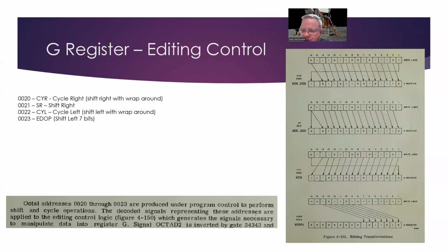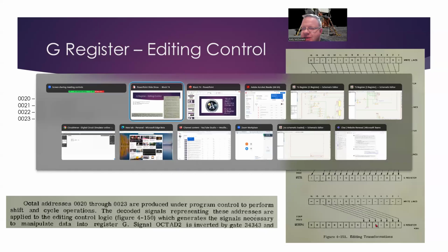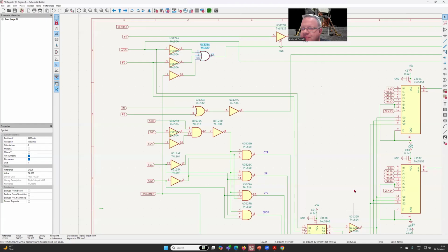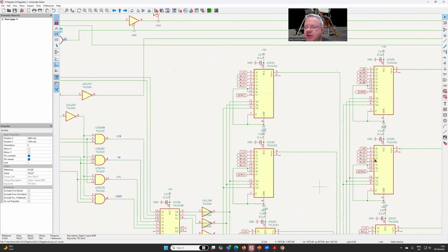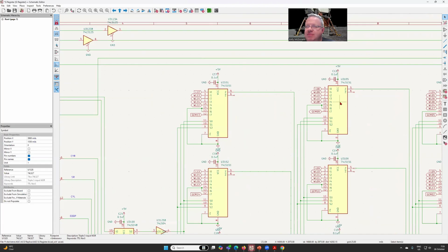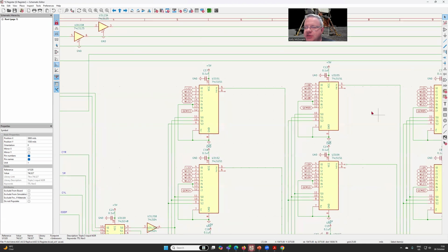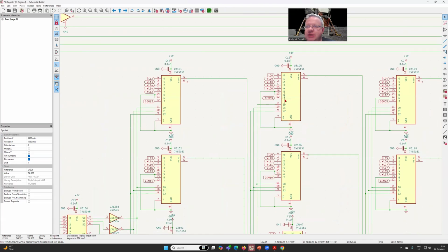And so what I decided to do is, again, to make it a lot simpler, and so I've made a few changes since the last time you saw this circuit. Before, I had a couple of quad 2-to-1 selectors, and then 4-to-1 selectors. And then I realized, okay, I could actually use these 74LS151s, which are 8-to-1 selectors.